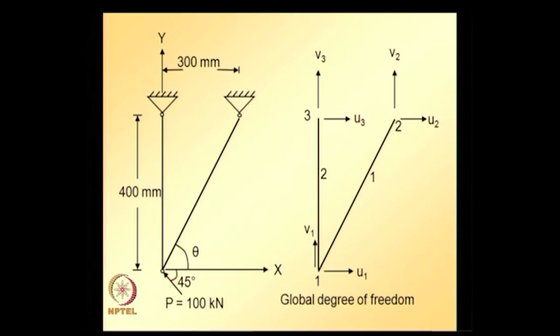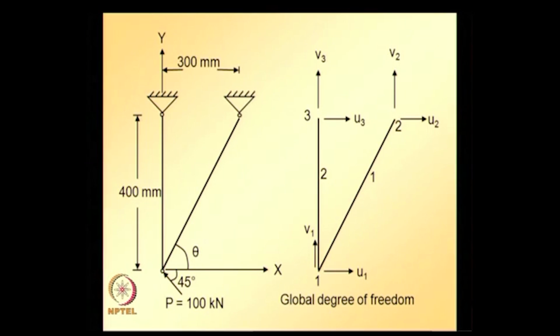However, if we choose to define element 2 to go from node 3 to node 1, then positive local axis for element is along negative global y axis, giving alpha value equal to 270 degrees. A consistent pattern for defining element connectivity is helpful when analyzing stresses with large number of elements. So the choice of local node numbers is very important.